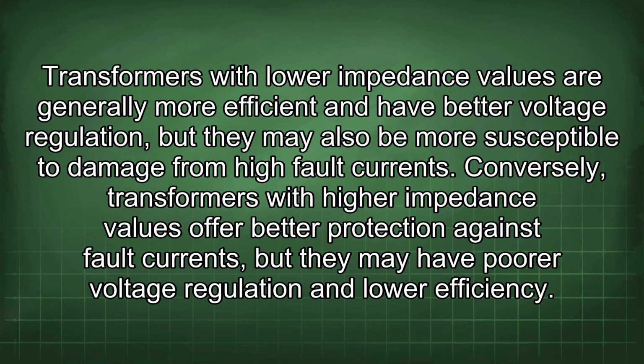Transformers with lower impedance values are generally more efficient and have better voltage regulation, but they may also be more susceptible to damage from high fault currents. Conversely, transformers with higher impedance values offer better protection against fault currents, but they may have poor voltage regulation and